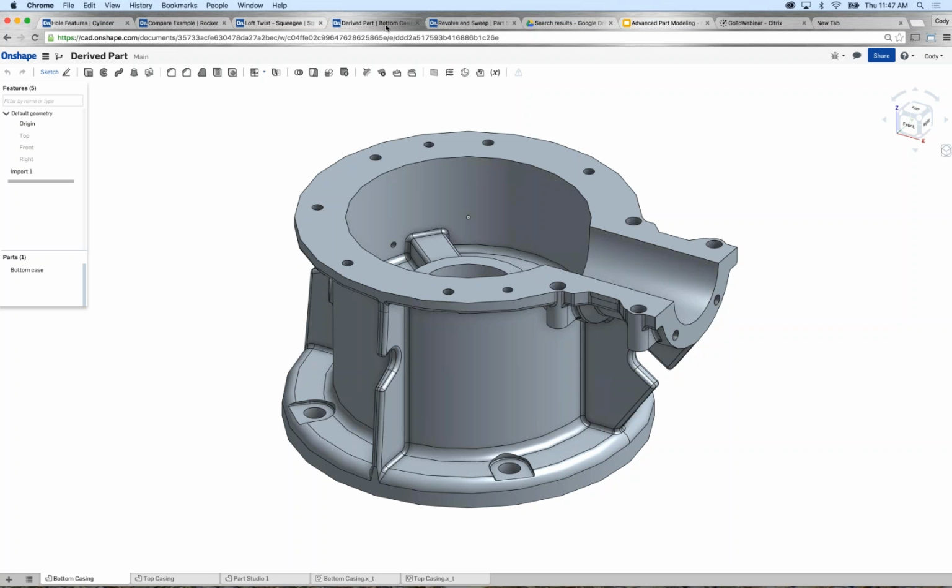So let's just say I've got two parasolids from a vendor, two totally different files. I need to put these files together and then build a part around them. And this is a common workflow. Maybe I'm getting motors from my vendor, I'm getting some bracket from someone, and I'm trying to piece all this stuff together to build my part around these things. This is a great example where derived features make a difference.